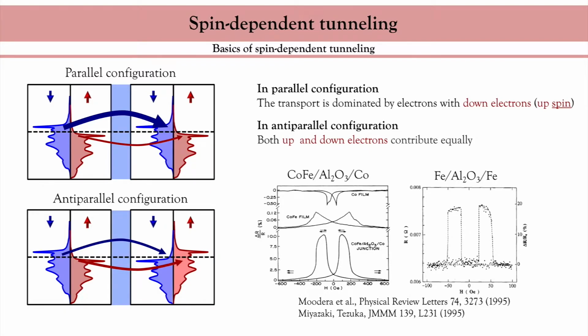First, it enabled the fabrication of highly sensitive magnetic sensors, much more efficient than metallic spin valves. Second, because the overall resistance of this tunneling device is quite high, it is compatible with semiconductor technology and can be used as a basic brick to build up hybrid spin-based devices embedded in semiconducting circuits.